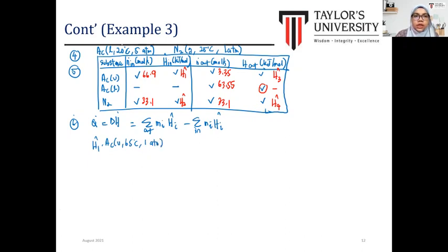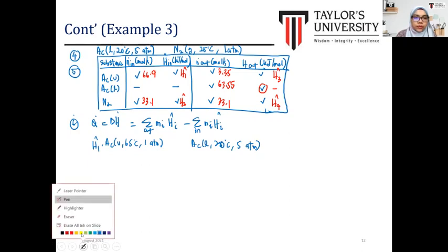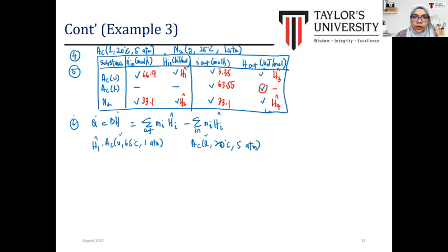So the initial or reference here, we have acetone liquid at 20 degrees Celsius and 580 mmHg. If we take a look at the terms here, we have a different phase, different temperature, and also different pressure. From the reference to the desired condition at stream 1, it cannot be changed simultaneously. That means you should perform it one by one for each term.